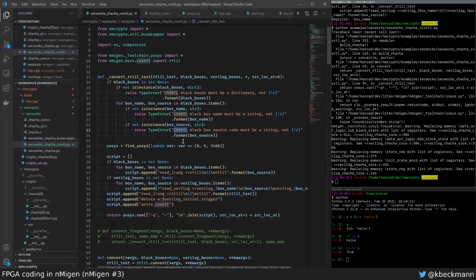The difference is that this hooks in very neatly together with the open source tools, yosys, which is a program that, I'm probably going to get the terminology wrong here, does the first stages of converting your HDL to something that is understandable by your place and route tool. In this case, we don't really care about an actual FPGA. We want it to run on C++.